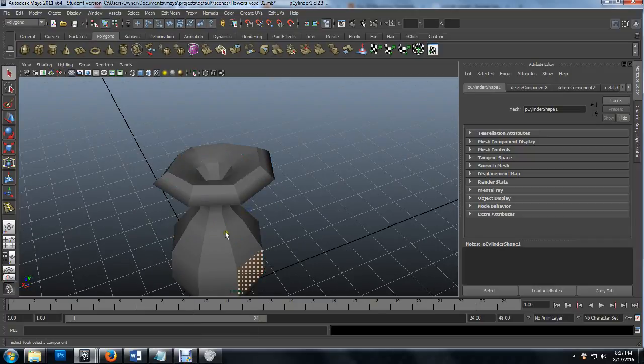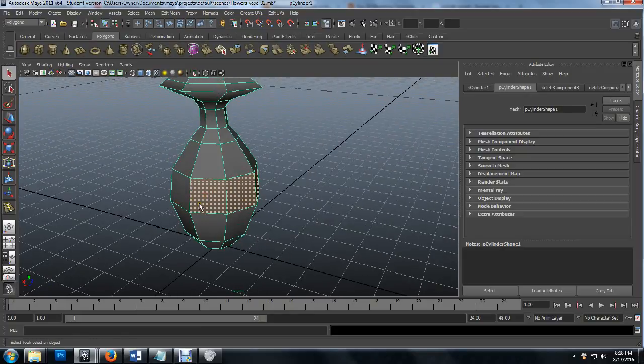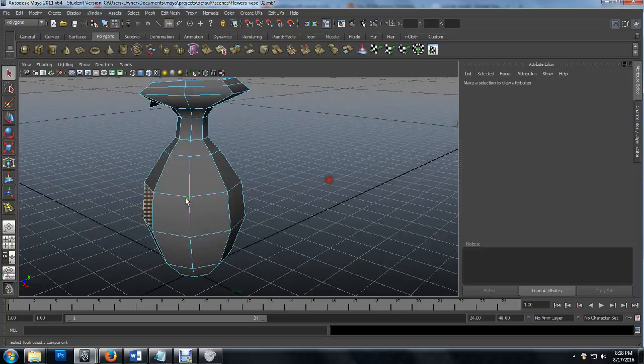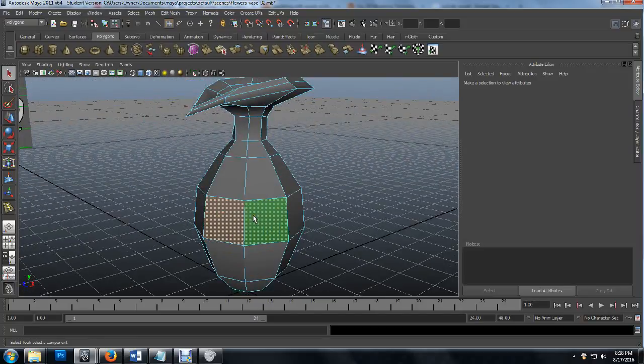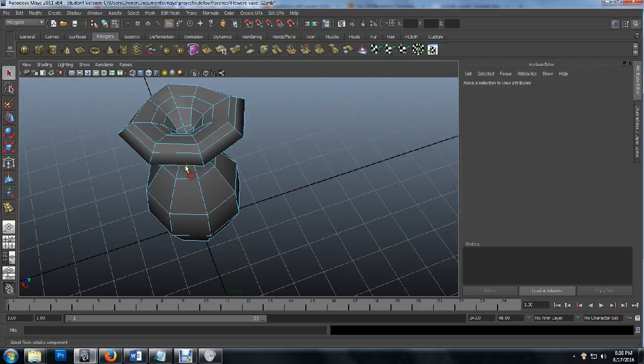Nice. Occasionally when you're working in Maya, you might have a face that is highlighted that just won't unhighlight. You can just jump into face mode and click it and then unclick it, which is what I'm doing here. No biggie. You might not even have these anomalies popping up, but they're driving me crazy, so I got rid of those. Alright, so all that geometry looks good.